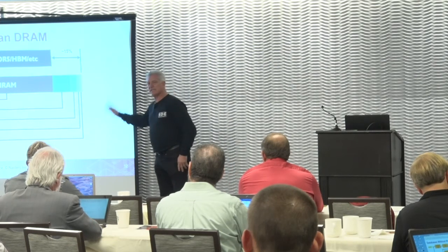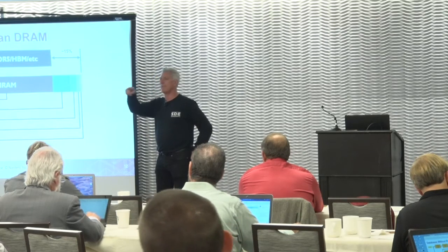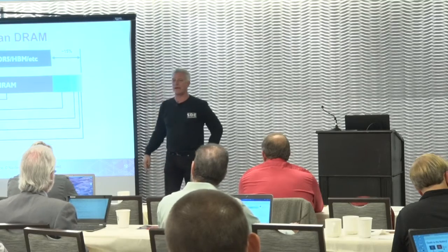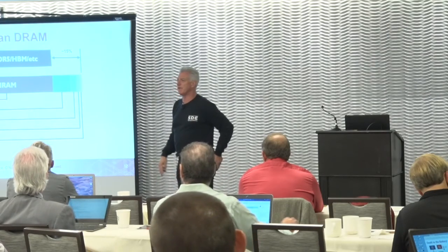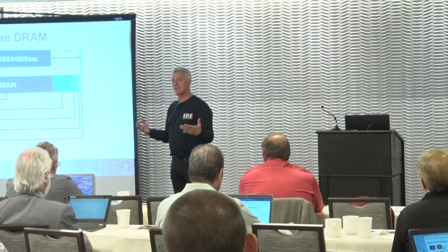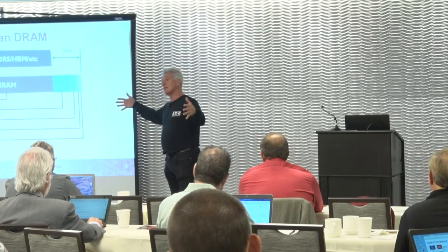The other things that we were able to take out of the architecture, and this might be good, I'm sure you probably have some telecom people in the room. Another thing is that we got rid of the four activations window. If you're a telecom guy, you know that the four activations window is really painful, because that says that once you've opened four banks, you can't do diddly squat for a long time before you activate the fifth bank, because of power supply issues. We don't have that. We took that out of it too.